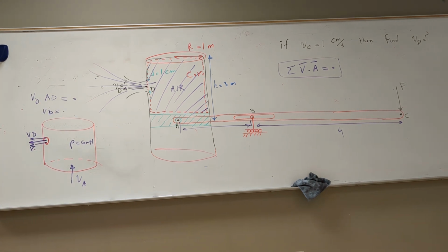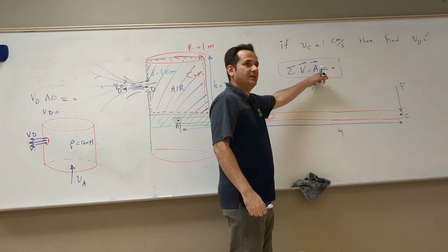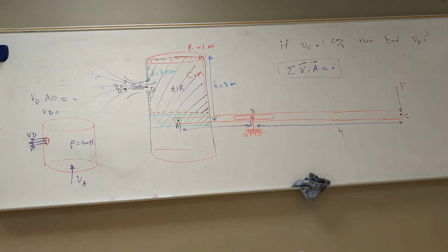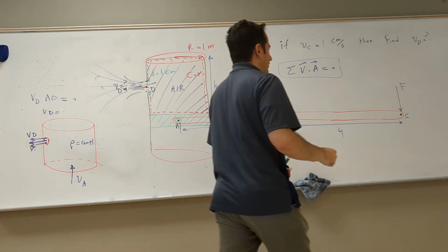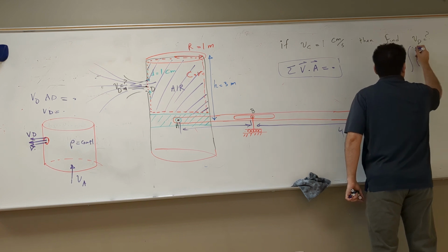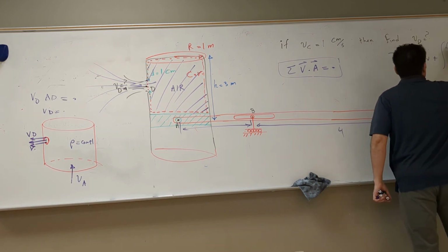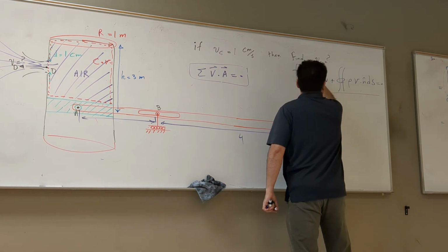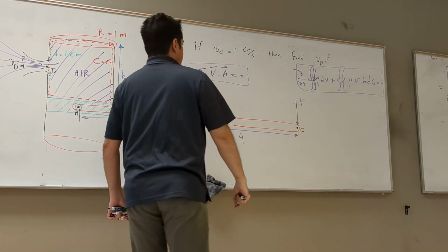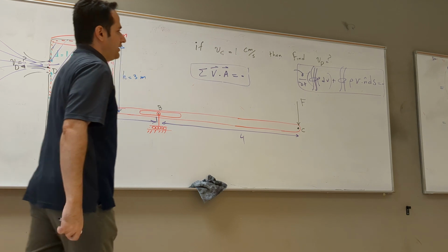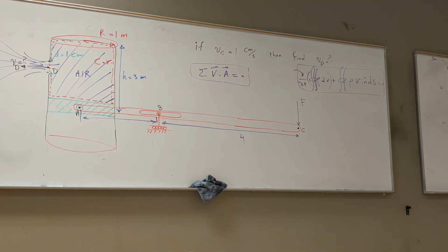But look, is this the correct form of continuity equation? What did you do to simplify that? So you have to say, well, you know what, I think it's messed up. You go back from scratch, the most general, glorious way of continuity equation. What was the most general, glorious way of continuity equation? d/dt of the volume integral of rho dV, plus the surface integral of rho v dot n dS, equals 0. That was it. And I took this d/dt inside, but you can keep it outside the entire integral. That's the most general form of continuity, and I'll show you why we got that.